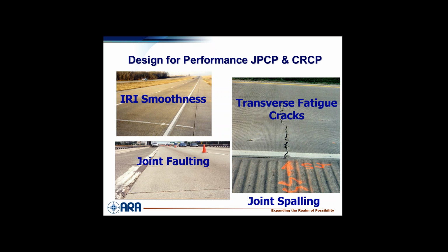The other one, this big one that's missing, that Professor Riesler and students have done here, is longitudinal cracking. That needs to be put into this. That's a really big weakness right now in this procedure, Jeff. And an important one because there's a lot of that happening when we widen out slabs for various reasons. And it's a really big deal.